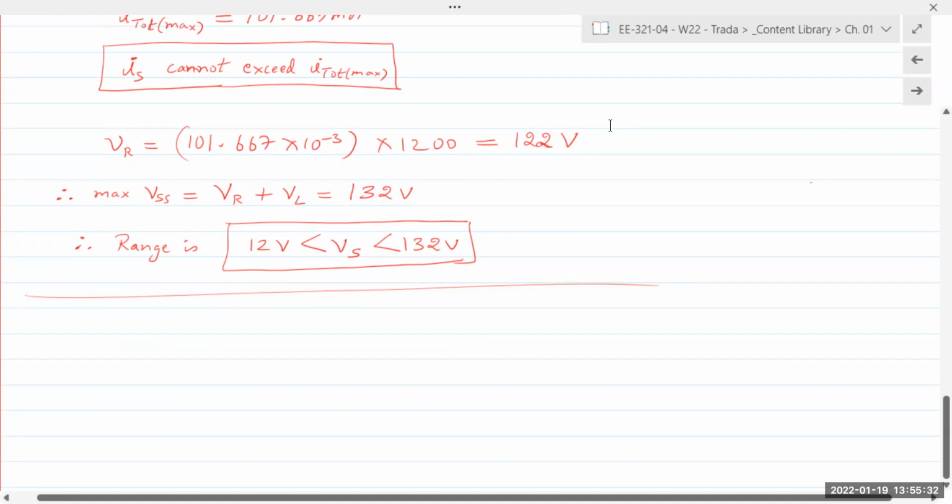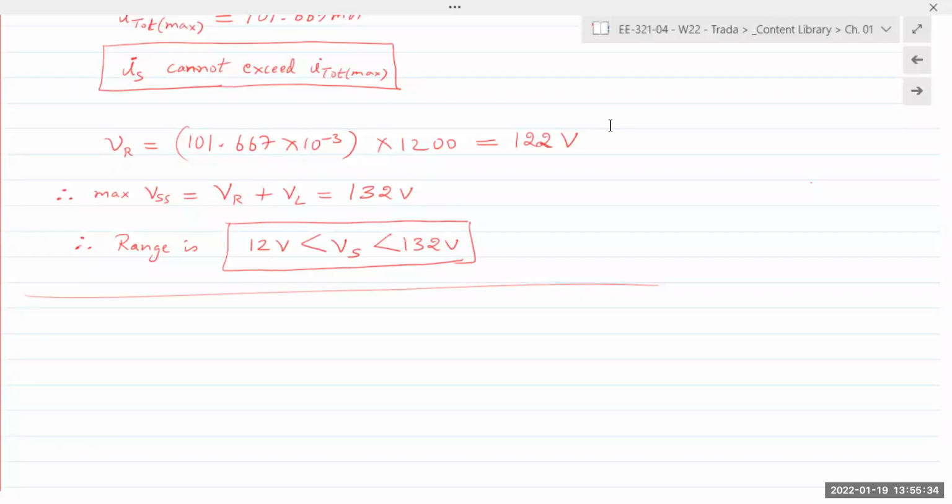IZ is equal to 0. Everything else, the voltage is going through the load resistance. So if the Zener is not on, all of the current is going through R and through RL. Just calculate the voltage drop across those two, and you find the current. So that's straightforward to do. I should not be using the word easy, but straightforward.